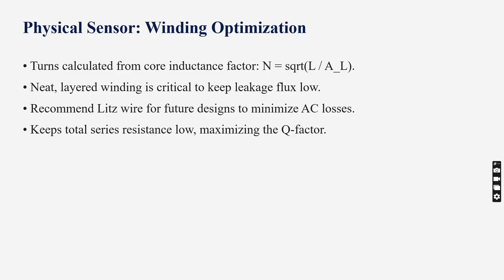The number of turns was mathematically calculated by using the core's inductance factor AL. Tight, neat layers are critical to reduce leakage of flux.